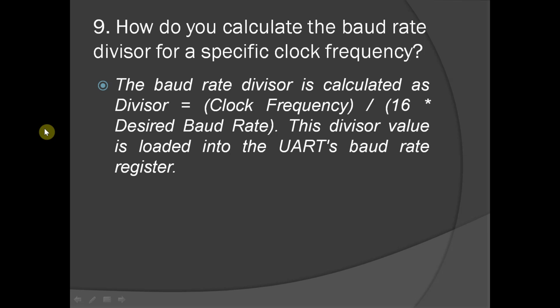Okay. So why can't we give the system clock signal to both the transmitter and receiver? Why can we only use this formula? We need a specific baud rate, right? Like how many bits or signals we need to send should be calculated, right? The system clock may be at a very high frequency, so we are basically decreasing the frequency.